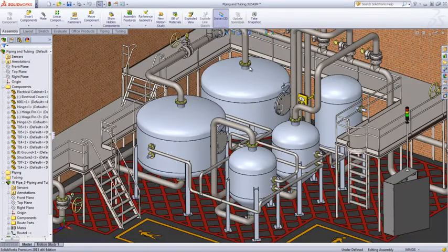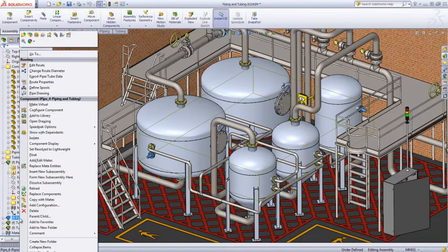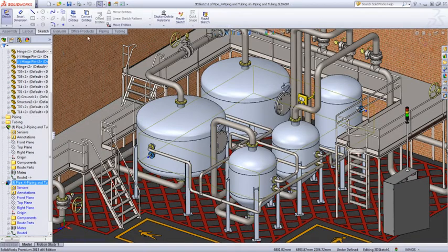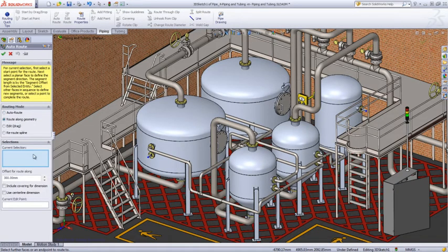A new option in the Auto tools lets you create pipes along an existing geometry, which is extremely useful for routing pipes in closed and tight environments. You simply need to select a start point and collect planar faces to define the path of the route. Each face that is selected will add an additional line segment to the route until you pick an endpoint.